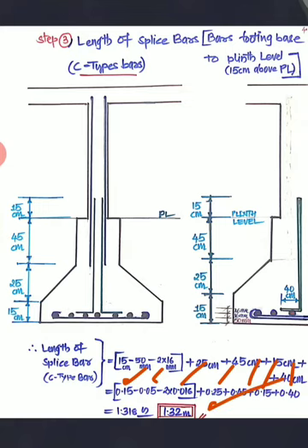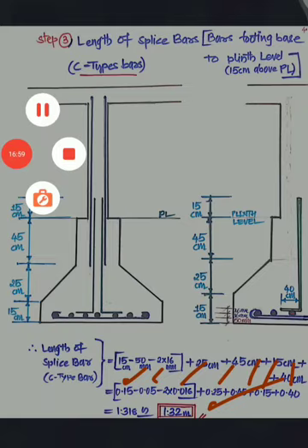So here also there is no need of determining the number of bars, as you will be having the same number of bars as in the columns. But one thing I'll tell you is how they are going to erect it. They are going to lay it into the mesh along the taper direction. I'll show you in the main figure.